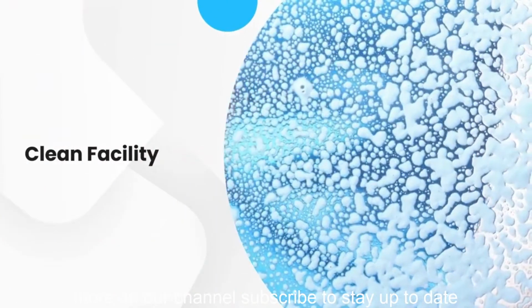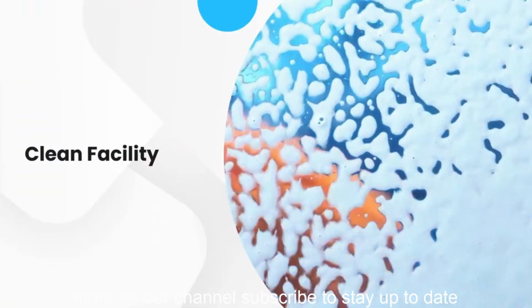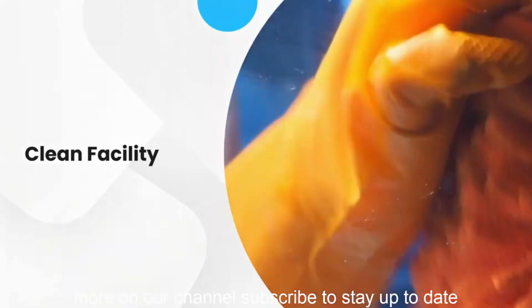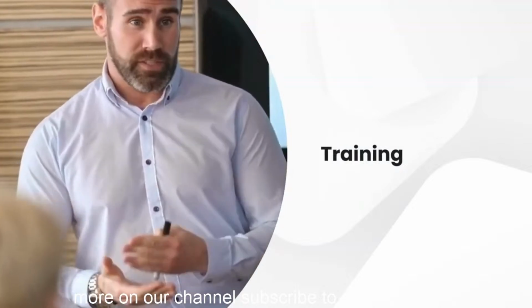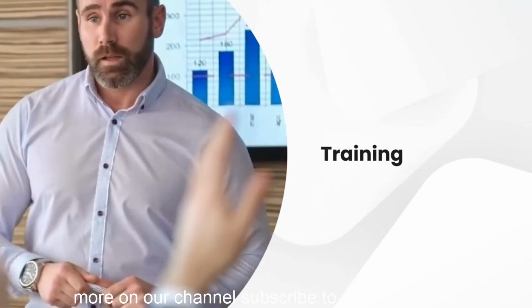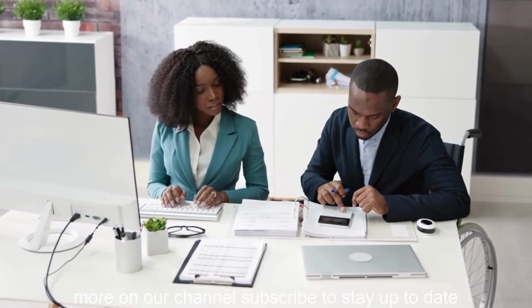Maintain a clean and organized facility. A clean and organized facility is a visual indicator of GMP compliance. Implement a robust cleaning and sanitation program and ensure that all equipment is properly maintained. Train your personnel. Your employees are your first line of defense during an audit. Ensure they are well trained on GMP principles, your company's procedures, and how to interact with auditors. Have a mock audit. Conduct a mock audit to identify potential weaknesses in your system and give your team practice in responding to audit questions.